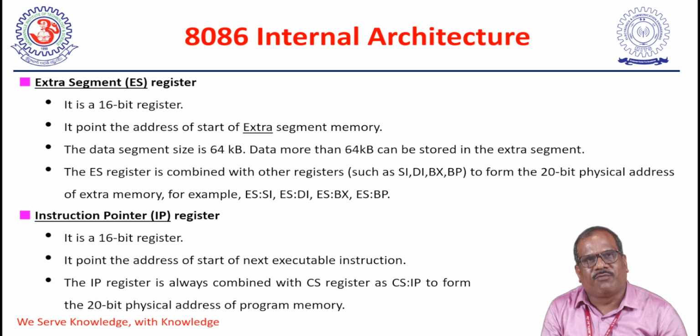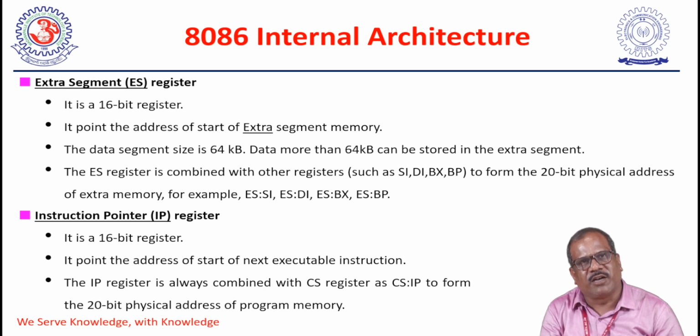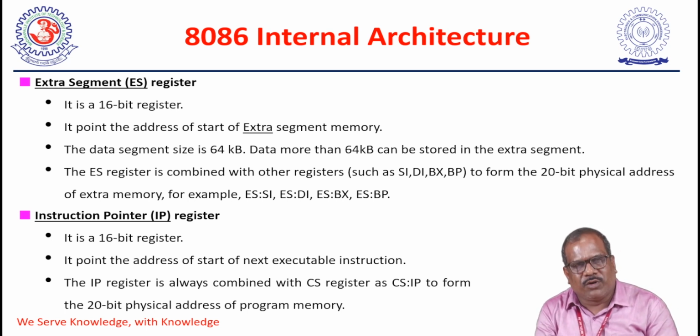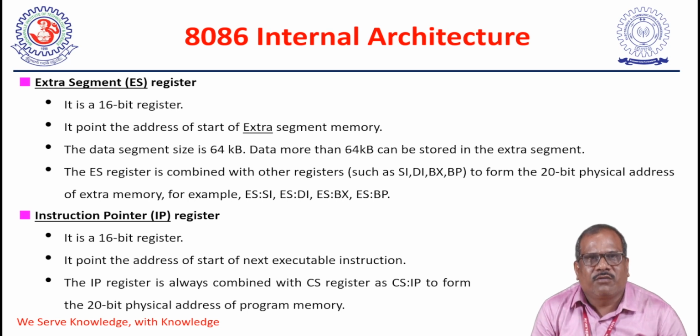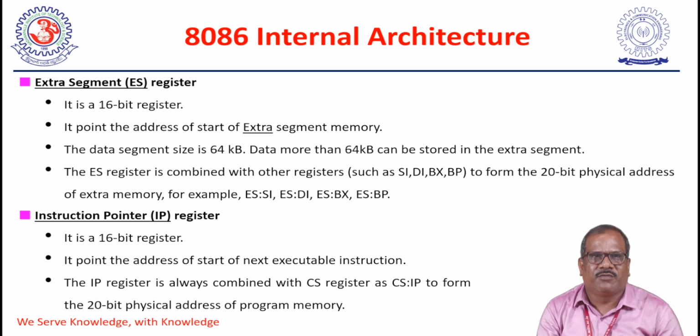So these are all the 4 segment registers used in the 8086 microprocessor. The 8086's total 1 megabyte of memory is divided into 4 segments. The segment registers are also used during program execution. During program execution, we can temporarily perform ALU operations with the help of segment registers.